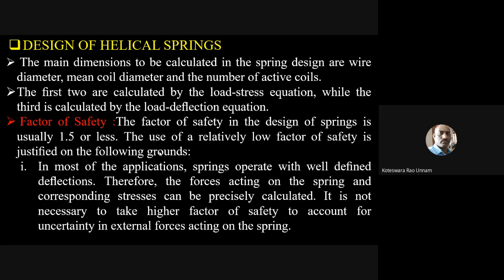It is not necessary to take a higher factor of safety to account for uncertainty in external forces acting on the spring. Generally we take the factor of safety to overcome uncertainties. Suppose I am unable to estimate precisely the magnitude of the load acting on the spring. We know the stress is induced because of P. If you look at the equation for the stress, tau is equal to K into 8 P D by pi d cube.